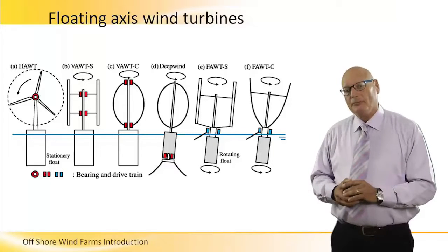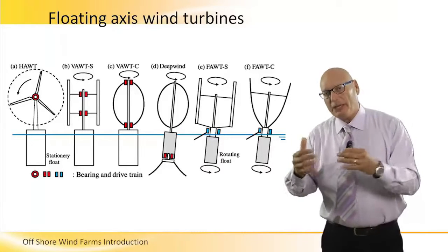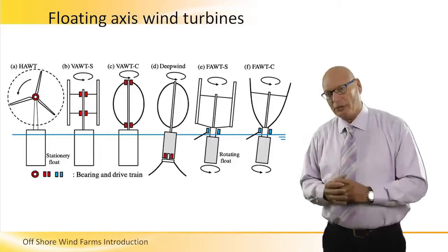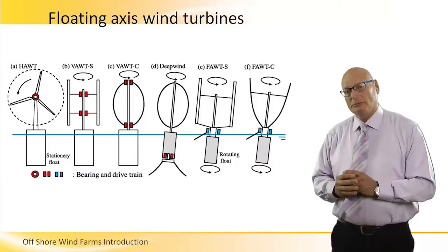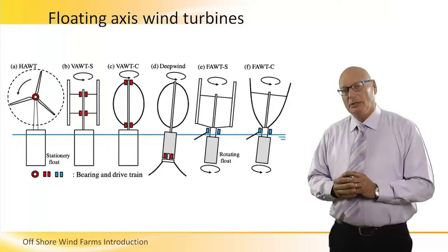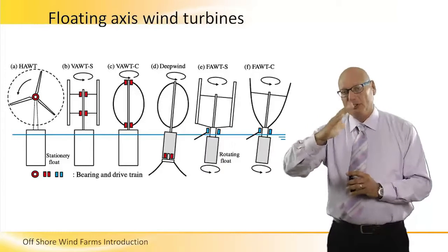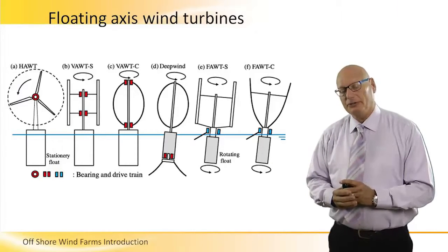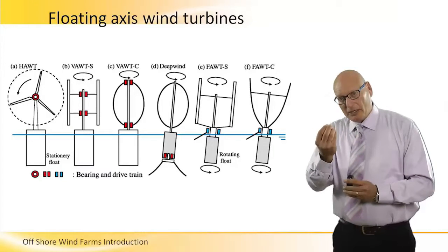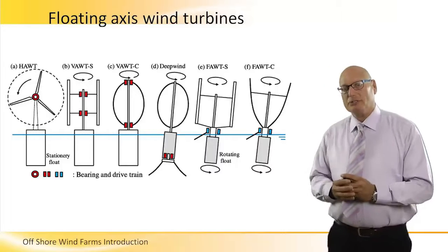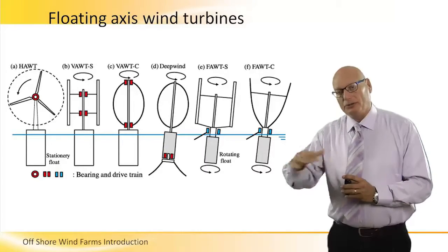sea level. Now, because vertical turbines receive wind from any direction as opposed to horizontal ones, they can easily float and change their position. Wind comes from different directions. Their efficiency is not dropped dramatically if their position is varied. So that's an advantage for the vertical ones. Being able to receive winds in all directions and able to install them floatingly on the water.